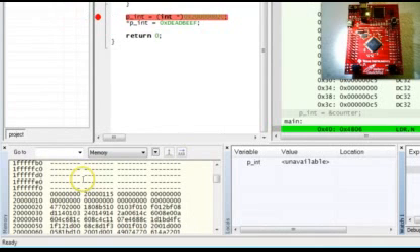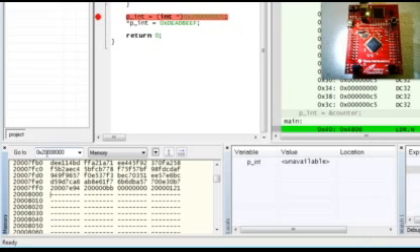Indeed, you can see a hole in the address right before the beginning of RAM, which simply means that the debugger could not read anything from these addresses, most likely because they are unused. When you probe further at the address hex 2000, 8000, you can see that the RAM ends. So it is an island extending for hex 8000 addresses, which is 32 kilobytes in decimal. This means that the microcontroller has 32 kilobytes of RAM. This is as much as you know about the addresses at this point.